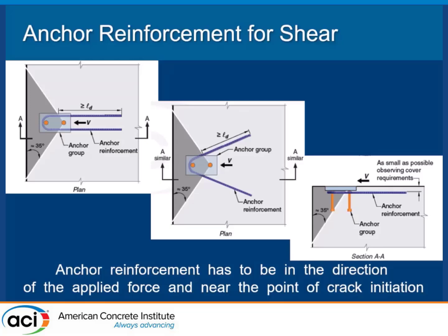Whenever I'm nervous about anything, put in a hairpin. If you put it right up against the anchor here, that force is directly transferred to this, okay? So you don't even have to develop anything here. All you need to do is make sure it's touching, and then you can take it back wherever you need to, however you need to in shear. You don't quite have that opportunity with tension with anchors coming down, right? There's nothing, you can't grab it, right?